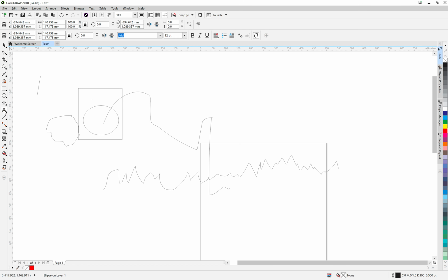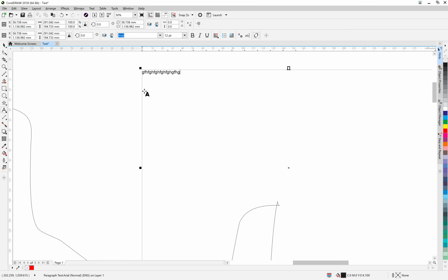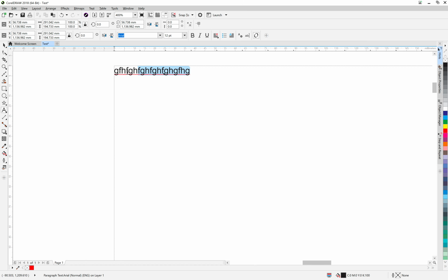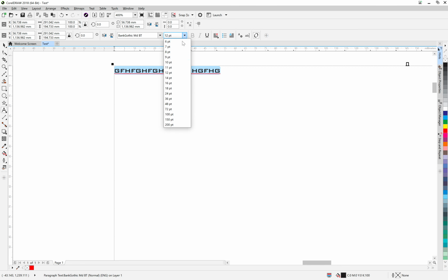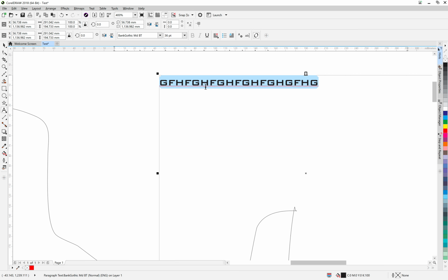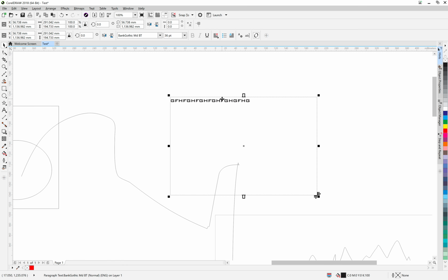What else have we got down here? Text tool, very, very important. If you click on the text tool, you can come across and draw a box, and that will contain the text. Let me zoom in, rolling in with the mouse. There we go, you can see that. We can highlight the text and move up to the standard toolbar area, where you can see the different fonts we've got loaded in. I can select a font, select the point size, and select things like italic, underline, bold, if those are options for that particular font. We won't be using the text tool in this particular way.